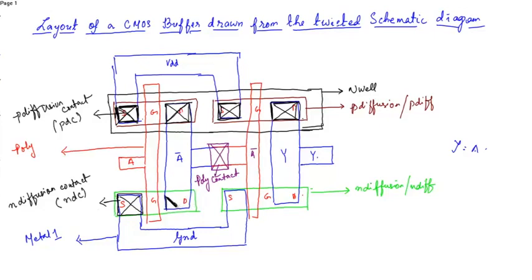So similarly over here, place one contact. Even in the NMOS we have 2 junctions each, so there will be 4. If a junction is not connected, or it has been placed in common P diffusion and N diffusion, then you do not require these contacts.